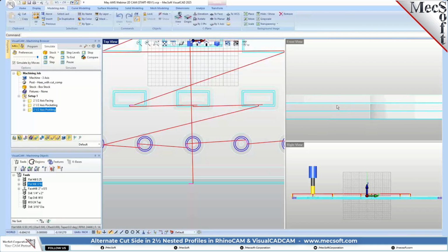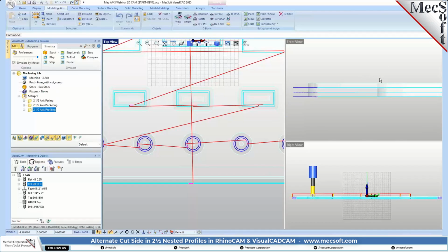Just a quick note there, Don, on the cut levels. Some people get confused, thinking the cut depth is an absolute value, but in our system, the cut depth is actually the coordinate value, with respect to your 0. That's why Don had to specify a negative value, which means you're cutting below the 0. That's an important distinction. The point where we want to start cutting is below our setup coordinate, which is at the top of the stock.